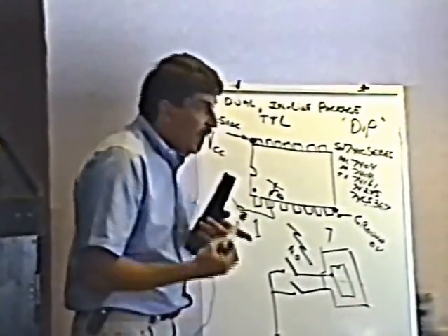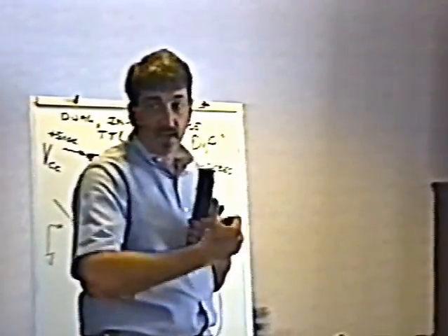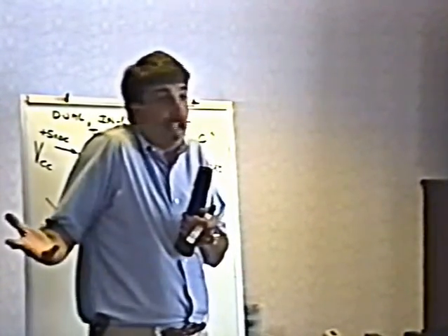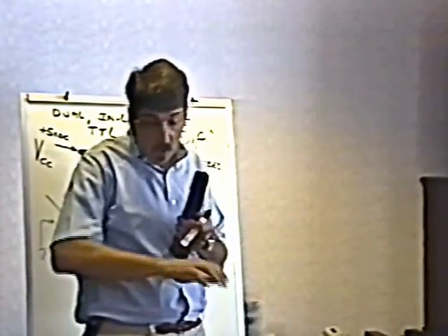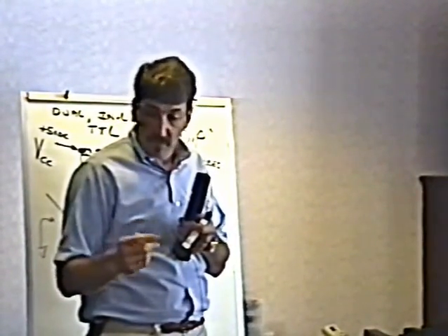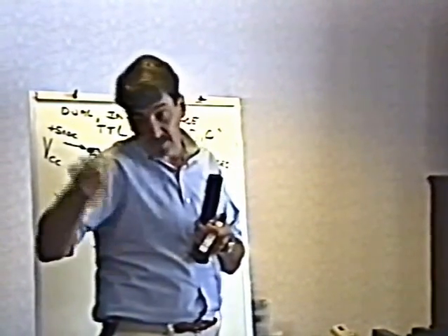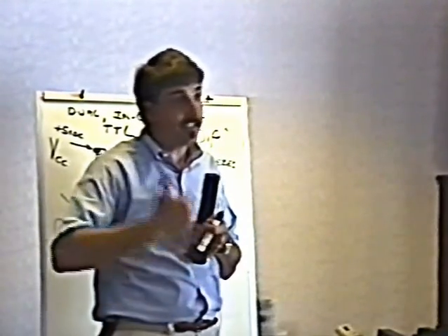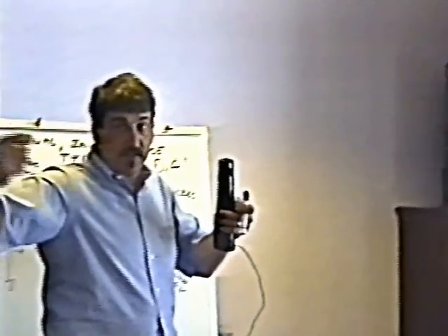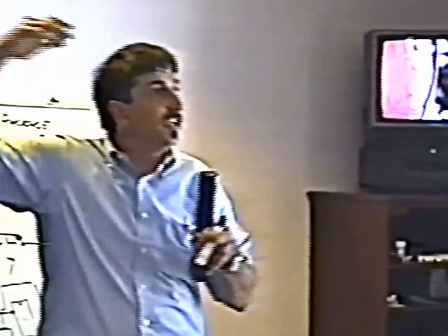Maybe you've seen this. You coin up the game, and you press the start button, and the guy starts to move right by himself, or left, or up, or down. And so you go, well, that's easy. It's a joystick problem, right? So you open up the control panel, you examine the switch for move right, looks perfect. You meter it, it meters perfect. You take the wire off, let the wire hang in the air, you try coining it up, it still moves right by himself, with the wire hanging off. So you hold the wires this far apart thinking that the air is conducting or something like that. You don't know what's going on, still does it.